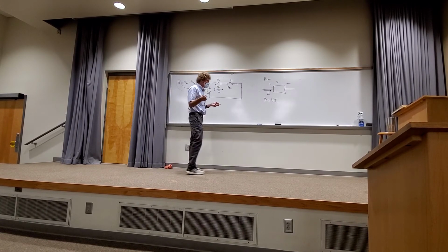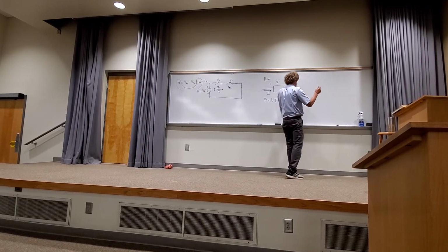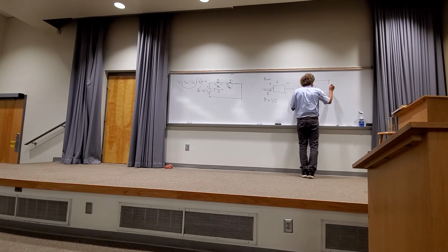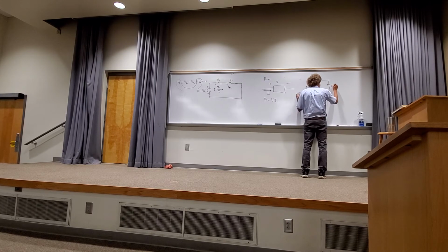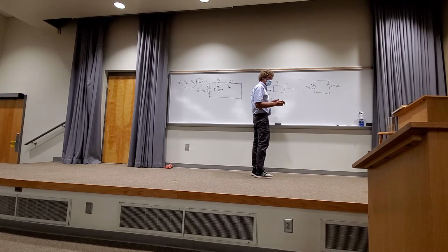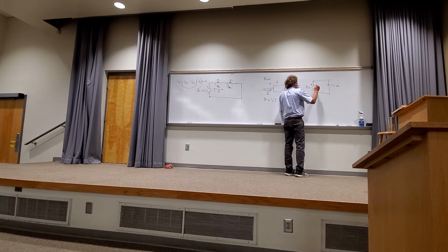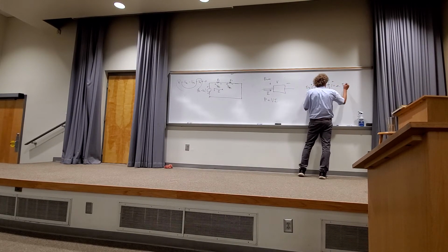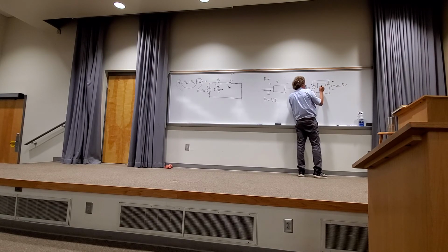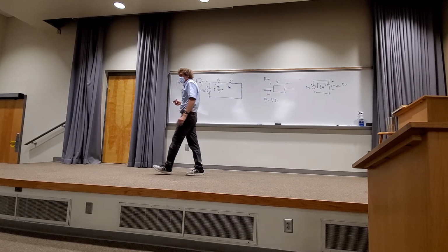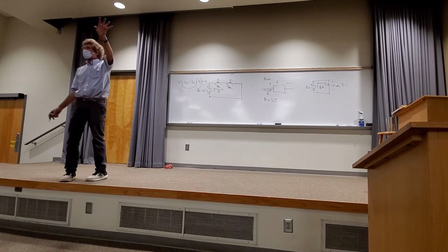So, if we take a look at something as simple as possible, I'm going to just put a voltage here of 5 volts, and I'm going to put a resistor here of 10 ohms. When I take a look at that, I'm going to see I get a current here flowing this way. This would be a plus to minus voltage of 5 volts across it. I get a current I, and it would be what? 1/2 of an amp. Do you agree with me? It would be V over R, right? How many see this? In the back, you with me on this one?